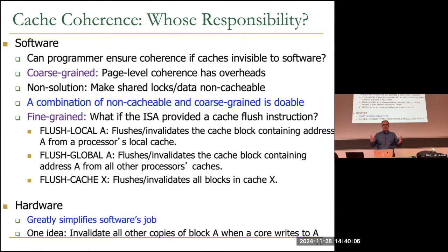If you have the coherence protocol at the level of words, you could potentially fix that problem, but it comes at the price of huge overhead to the design. So it's always a trade-off, and good to think about it.